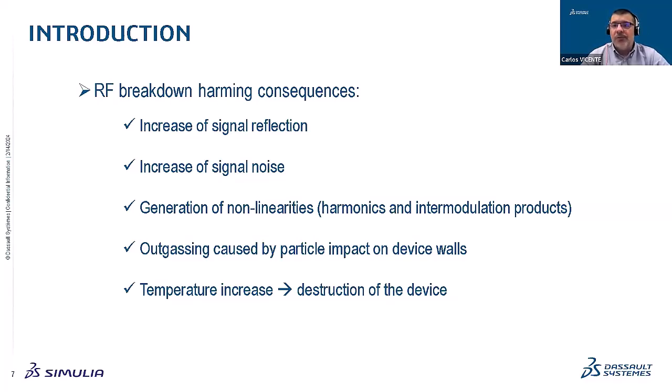On top of that, the discharge is also a highly nonlinear phenomenon, so it will cause nonlinearities in the system, like harmonics or intermodulation products, again degrading the performance of the component. Even in the case of multipactor, electrons bombarding the device walls can increase the pressure inside, and then can eventually lead to a gas breakdown.